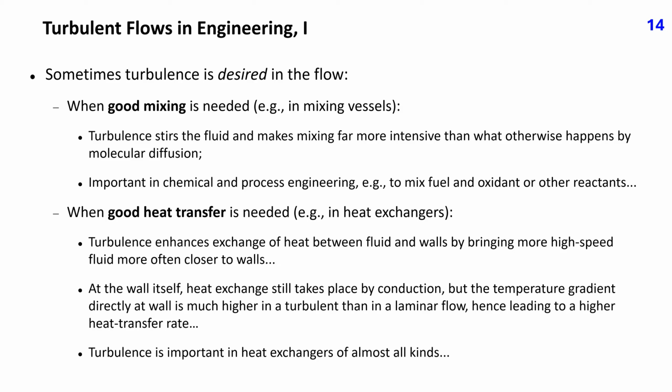At the wall itself, heat exchange between wall and fluid still takes place by conduction as in laminar flow, but the temperature gradient directly at the wall is much higher in a turbulent than in a laminar flow, hence leading to a higher heat transfer rate. The same is true if the wall is cold and the fluid is hot. Turbulence is therefore important in heat exchangers of almost all kinds.